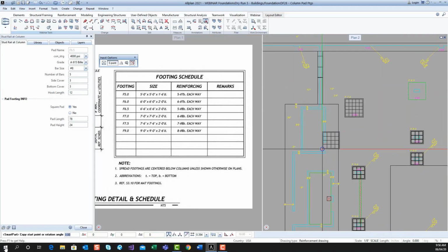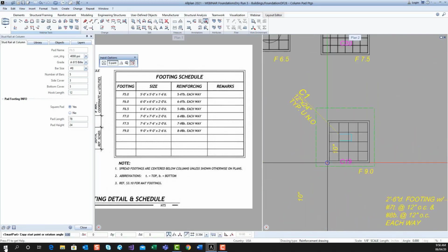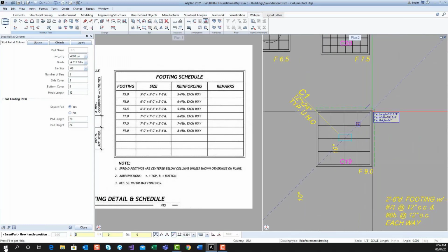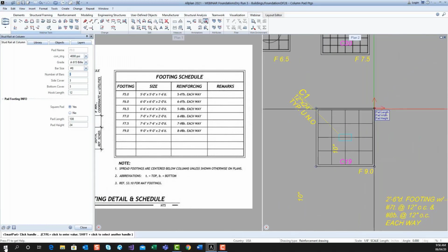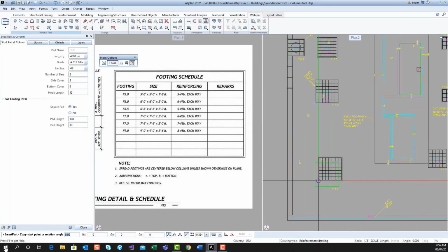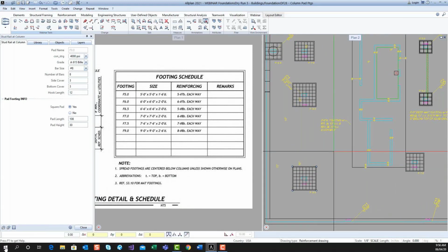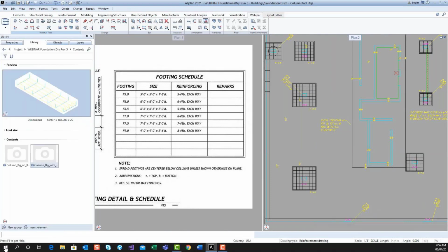So I'm going to pop in the 6.5 here, and then I'm going to place the nines. Again, dynamically pick the point, drop it using existing CAD lines. Everything changes automatically, such as pad height, etc., and then it's going to go ahead and fix it accordingly. As part of the smart part, we do have the ability to do a rectangular with longitudinal number of bars and segmented. Again, we can have a smart part that is built with top, bottom, hooks, no hooks, chairs, all that.